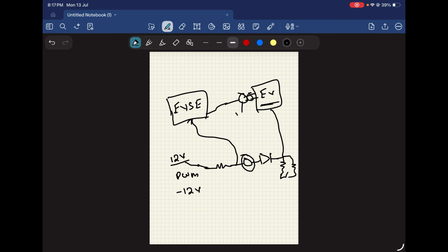Whenever it is connected properly, this 12 volts will flow this way via this ground, and here it will generate 9 volts. We should arrange these resistors R1 and R2. Once this 9 volts appears here, the EVSE will measure this 9 volts.